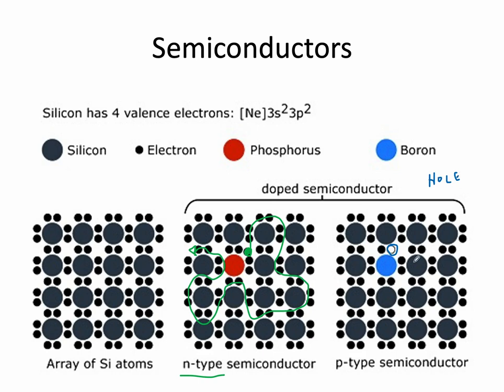You're like, how does it get passed around? Well, for example, this boron here may steal the electron from here. Now, this one would have a hole. And this silicon's like, no, I don't want the hole. So it steals an electron from this one. Actually, that's a bad example. This one over here to replace that one. So what happens is this hole actually travels around this crystal as well because nobody wants to have that missing electron. Everybody wants to have their octet.